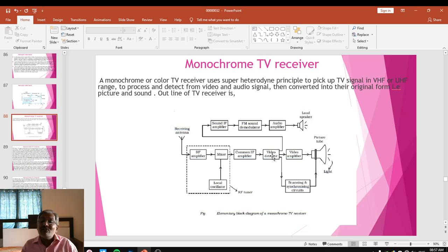Here, the video signal so separated is demodulated. As we are aware, the video signal is amplitude modulated. By using an envelope detector, one can separate the carrier frequency from the original video signal, and the video signal so generated now contains the sync pulses and the video signal.